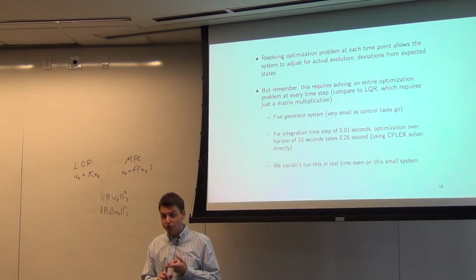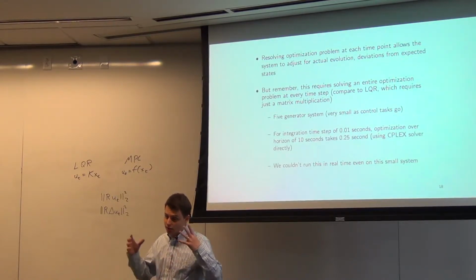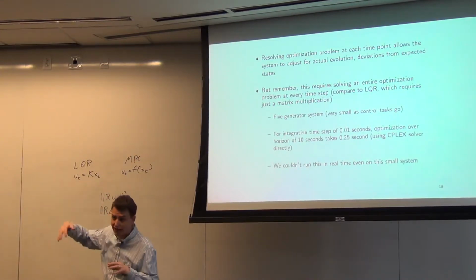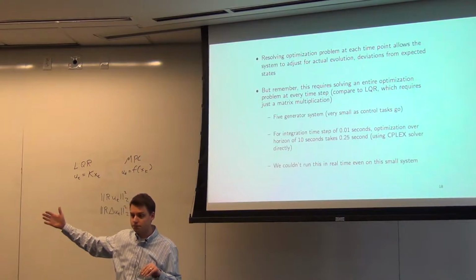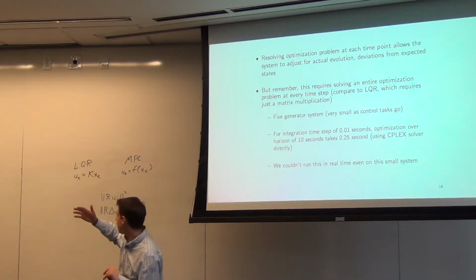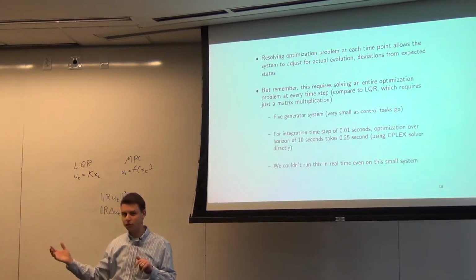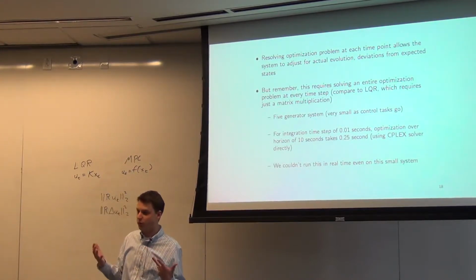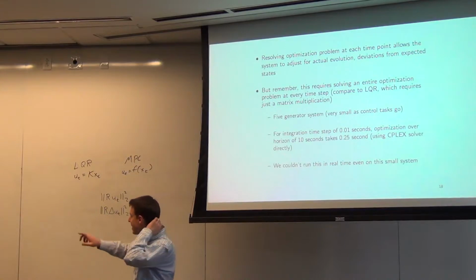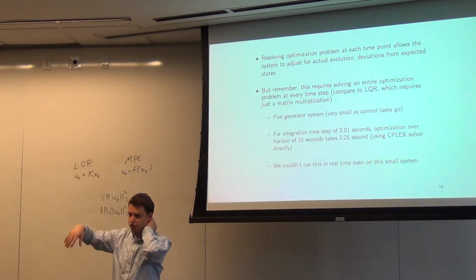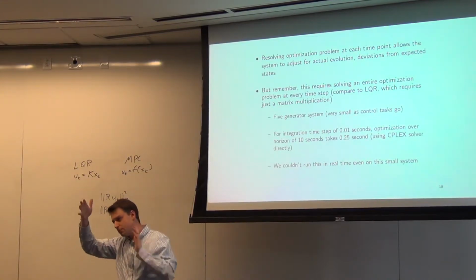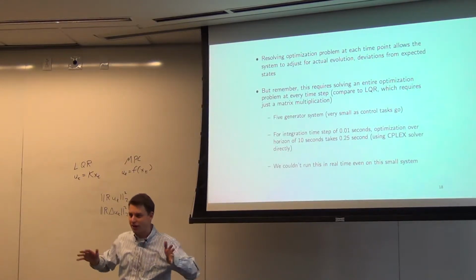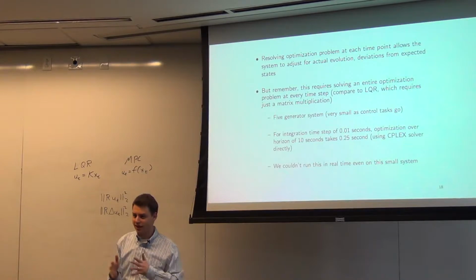This is an approximation which works pretty well in practice, just like LQR works pretty well even without knowing what's going to happen in the future. Even if the assumption of LQR were not perfectly satisfied, like maybe your noise wasn't exactly Gaussian, LQR can still work pretty well in practice because it has this feedback element. So if we drift away from the desired state, we push ourselves back there a little bit, sort of like a PID control does, right? A PID control didn't have any notion of optimality, yet it worked okay.